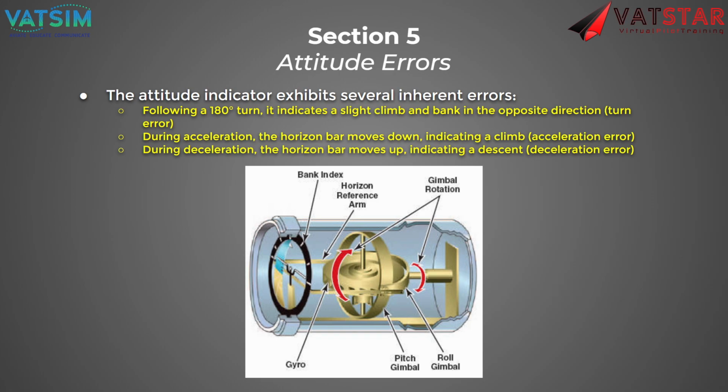That can just simply mean that you're pitched upwards. Yeah, obviously, at a slower airspeed, you'll be pitched higher. Yeah, exactly. That's why I was saying the attitude indicator may not always indicate whether you're climbing or not. It's just in relation to wherever you were. If you were to accelerate, it would indicate a climb based off where it was previously, if that makes sense.